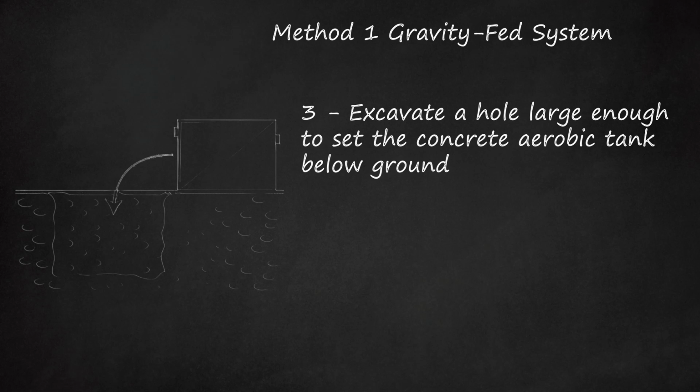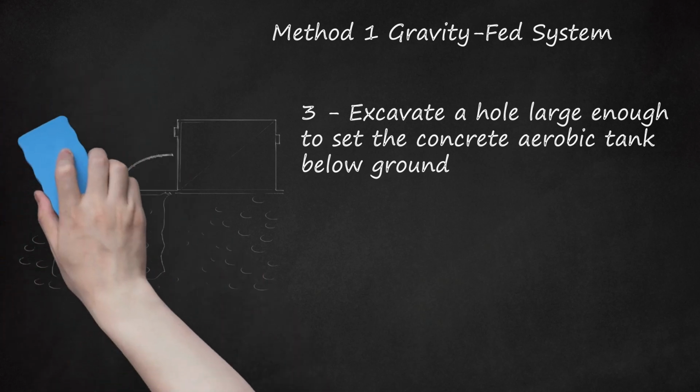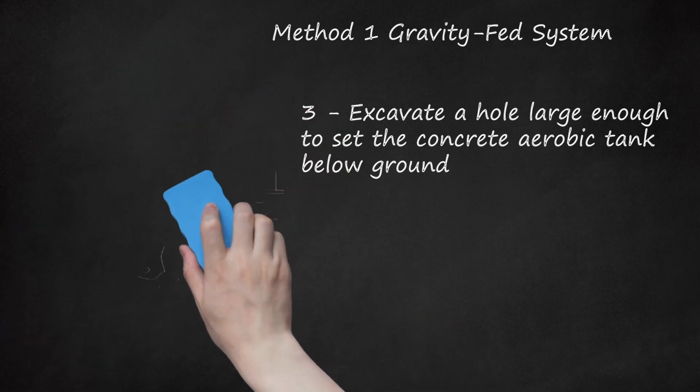Lay out and excavate your leach field as it has been determined by the test done in the permit process. When laying out and excavating, remember to maintain a positive flow between the tank and the drain field.